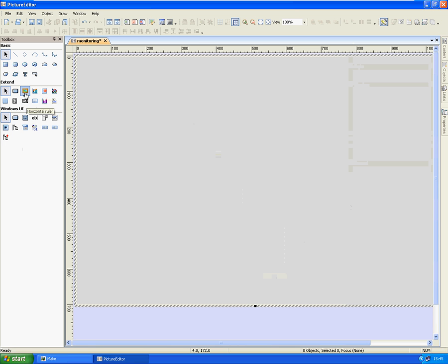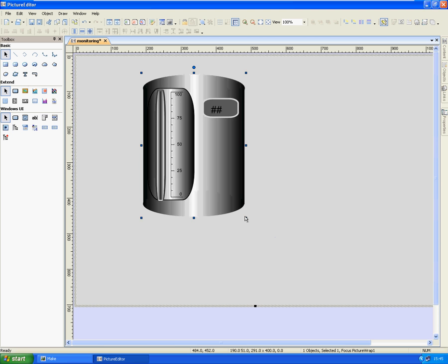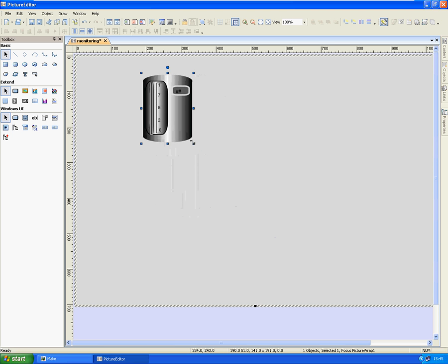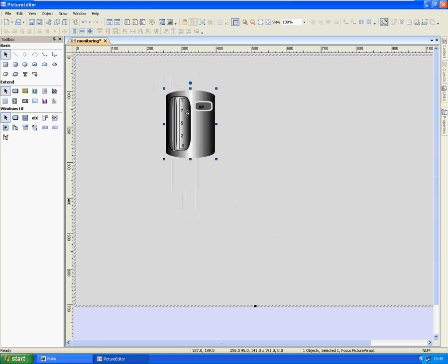Make flow picture. Step 1. Open the Object menu in Picture Editor and choose Graphic Model to open the Graphic Model dialog box. Choose the graphic model we created before and instantiate the model onto the picture.